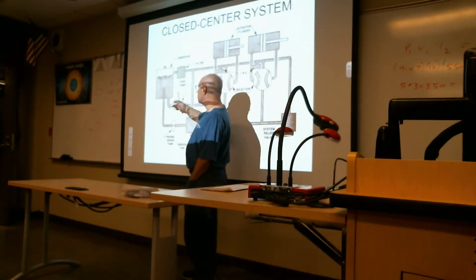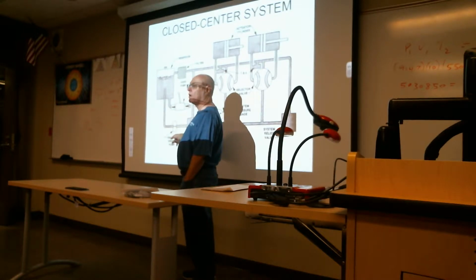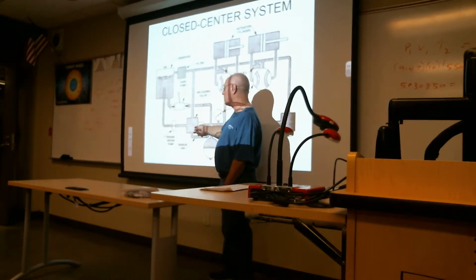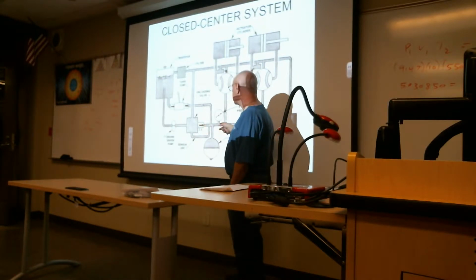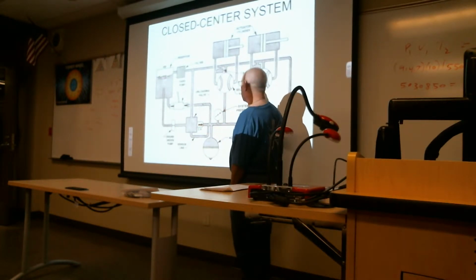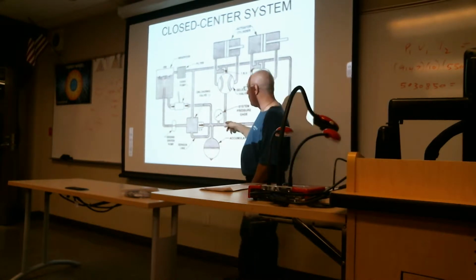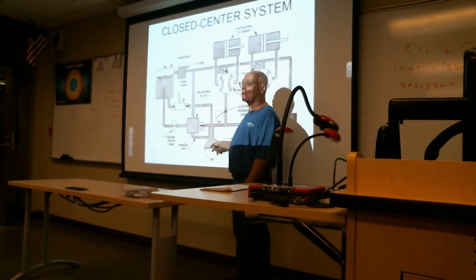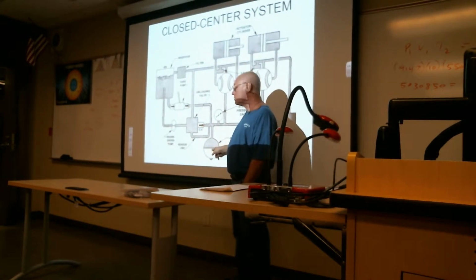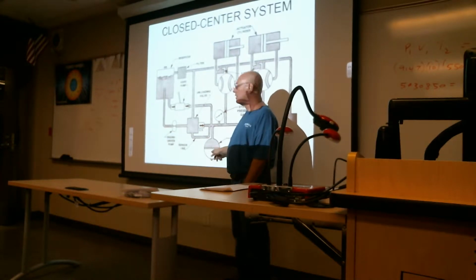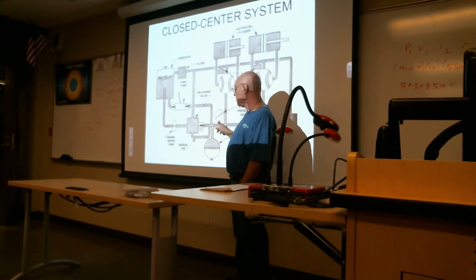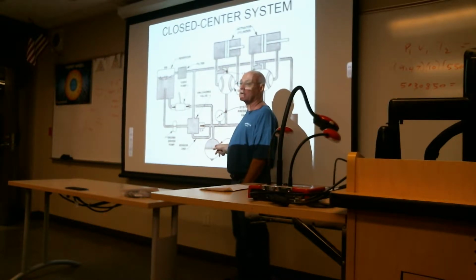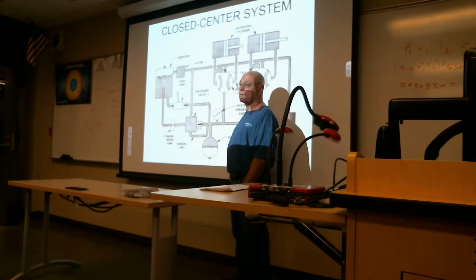The fluid from the reservoir passes to the engine-driven pump. The fluid flow then goes through a pressure regulator, sometimes called an unloading valve, and then the pressure is made available to the one side of the selector valves. Also, that hydraulic fluid enters into the cavity of the accumulator and pushes down a bladder or a diaphragm. So what we'll see happening is the pressure will begin to increase as the fluid is being confined in the circuit. So they call this closed center.